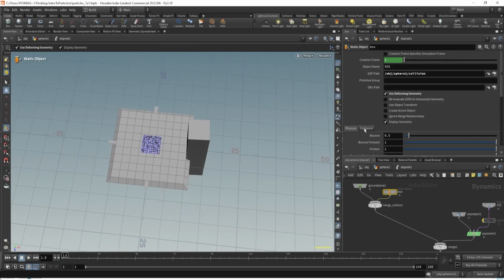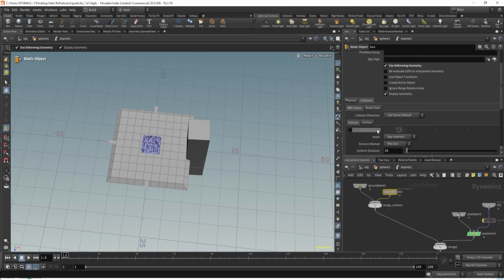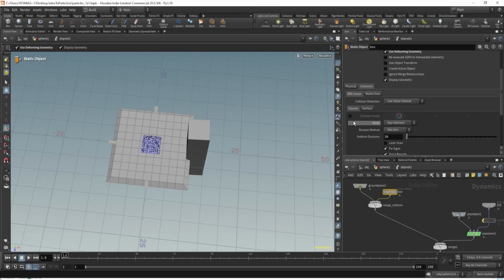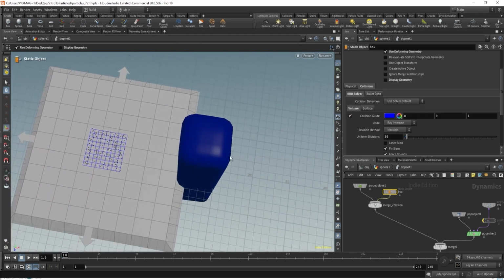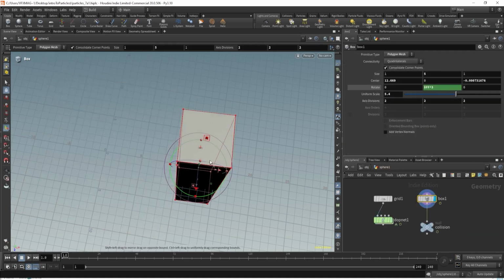And now let's talk about this collision tab. This is most useful over here and you will always have to check this. If I scroll down, I have some parameters over here and I'll ignore everything and just click this guide geometry. And let me disable this over here. So this is basically a collision. You have to always check this. And if you have any open polygon, let me delete.